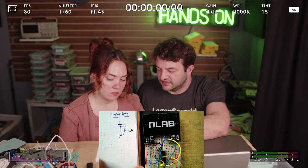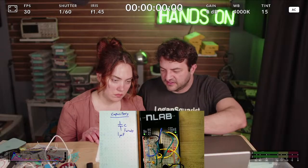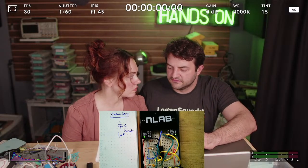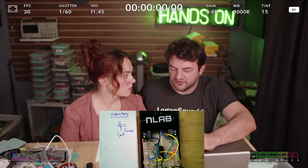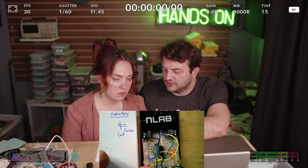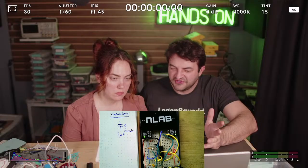So different types of capacitors do better at that. The capacitors in our circuit right here are called ceramic capacitors. They're little, they're beige. They come in small numbers like 1 microfarad. They have very little resistance. They call it ESR, or equivalent series resistance. But you can't get them very big. So if you wanted a 1 farad capacitor, it doesn't come in this type.